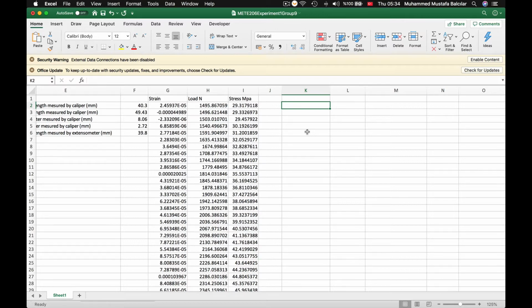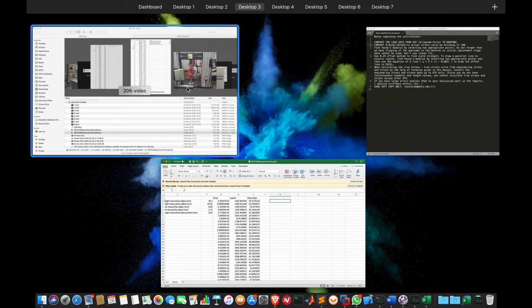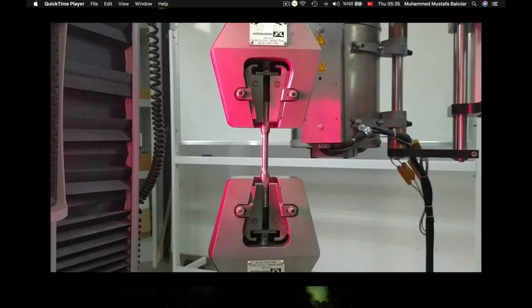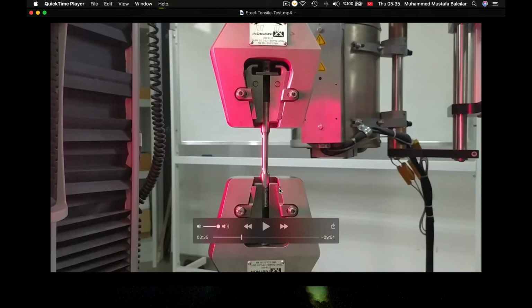One of them is, as I mentioned, the sliding of the specimen. So if we have the specimen during elastic deformation stage, it will not stay still. It will actually slide between these jaws, and due to the slipping, the elastic elongation values will be influenced.